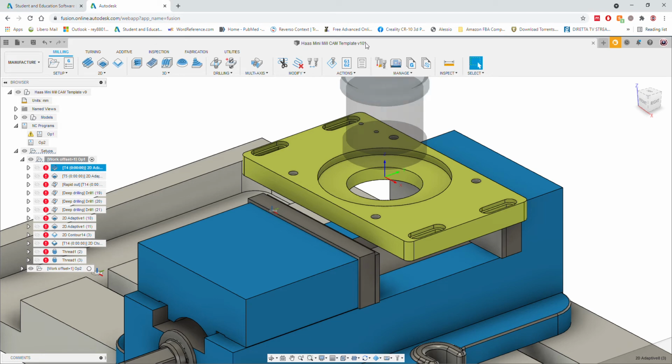So that's a 60mm face mill that we have downstairs to face your parts. Then you have a 2D adaptive just to make the pockets, the chamfer mill or spot drill to predefine the holes, and then some drilling, contouring, to de-chamfer.